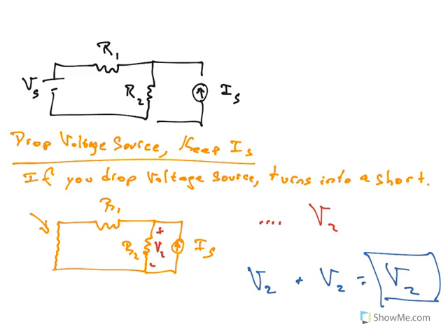Given a full circuit with multiple sources, break that circuit up into individual smaller circuits, each one of those having only one source. For each of those circuits that you've just drawn, solve the problem you're trying to solve. Once you have all of those solutions, you add them all up. That gives you your total final answer for the problem.